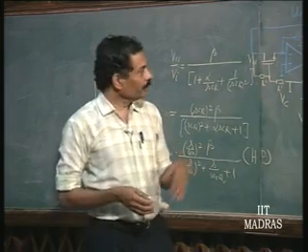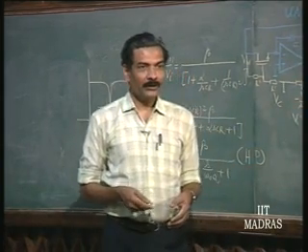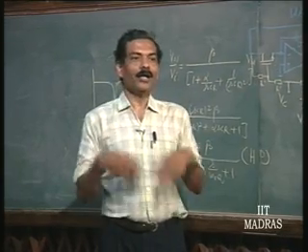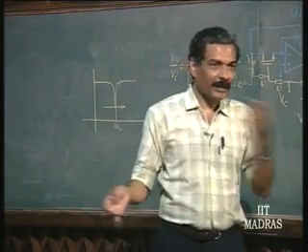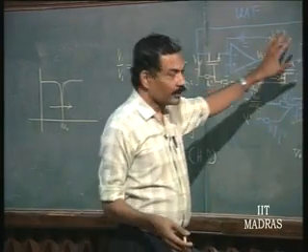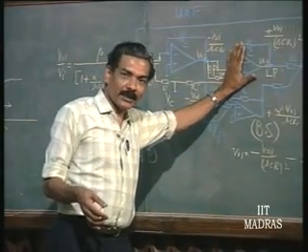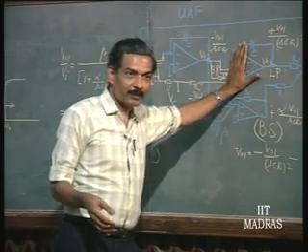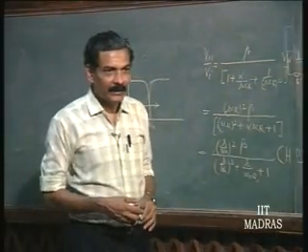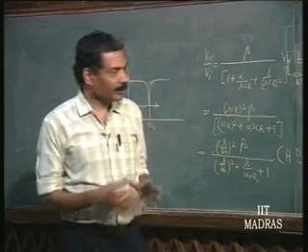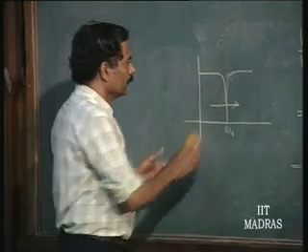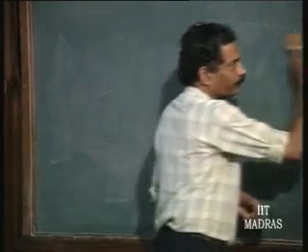Or if you take the band pass output, you can find out the fundamental or the harmonics. So, it can become a spectrum analyzer. So, it can be used as a harmonic analyzer or as a spectrum analyzer, the sweep voltage being given as Vc. So, it has considerable amount of application in signal processing.